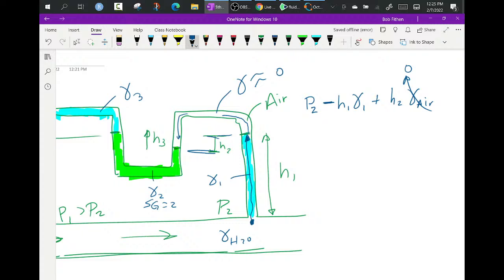You thump it with your finger to get those bubbles out. You shake it sometimes. If you look through the manometer tube, you want to try to get the bubbles out. The thing is, the bubbles can have this ability to stick in there, sometimes air bubbles sticking there because of the surface tension between the air and the water. But we all have water. So that's something to pay attention to, because if it was very small and you didn't, you would have the wrong number. So we got to this point.